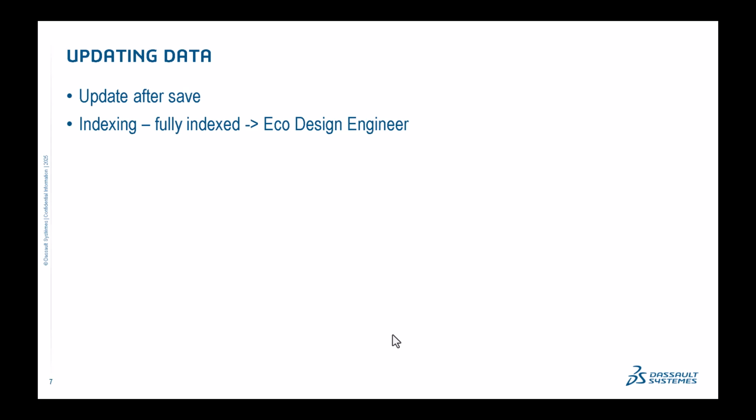It is important to understand that your models must be fully indexed and updated after saving to the 3DEXPERIENCE platform in order for the applications within the Eco Design Engineer role to be able to read the mass properties information of your models. For this reason, it is recommended that you allow time for indexing after saving your SOLIDWORKS models before opening these models in the apps that make up the Eco Design Engineer role.